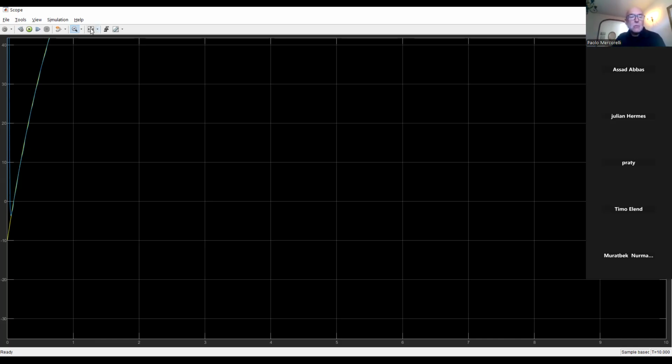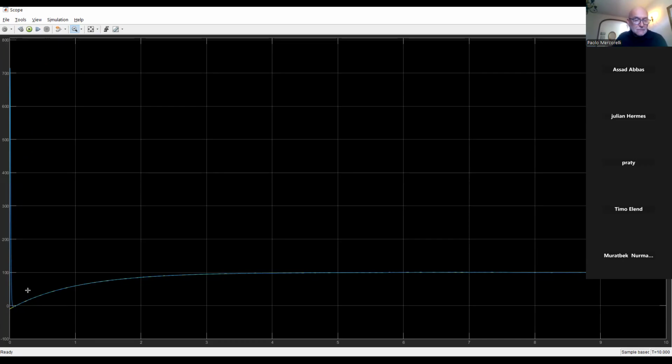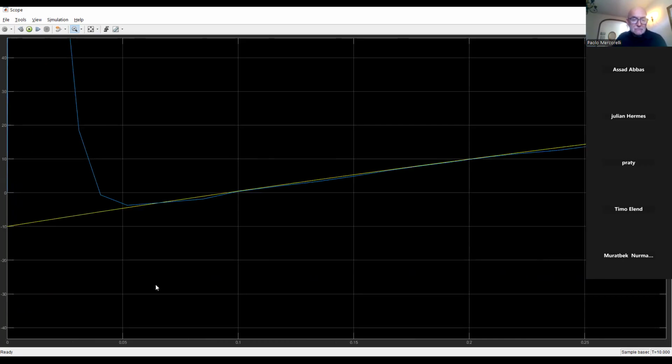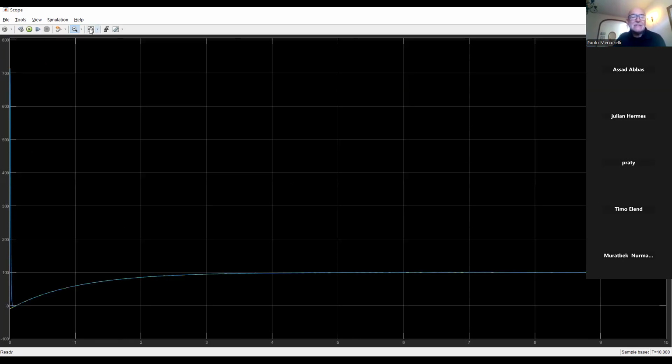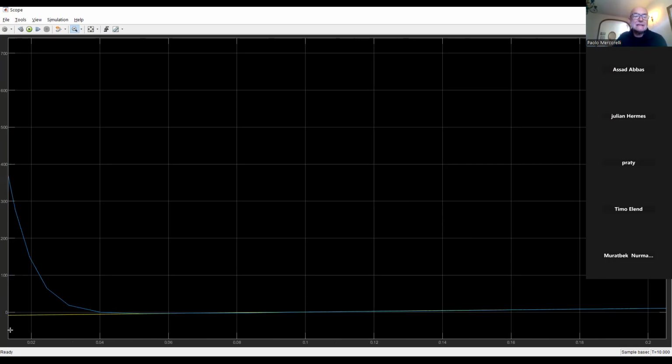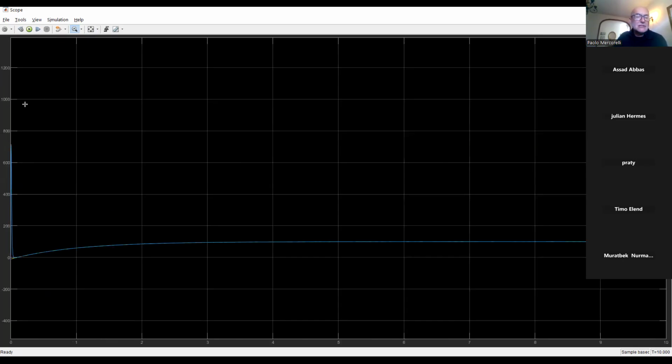The last thing which I want to show you, look here. Here we achieve, let me say, good result. Let me formulate this in this form here. Relatively quickly, 0.05. But we pay this result with a peaking. It could be that this is 700, remember here, is not acceptable. What we can do, as I told you at the beginning, I can place arbitrarily the eigenvalues. This means